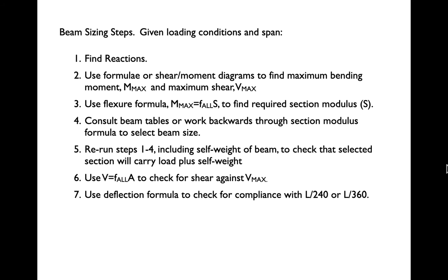And then finally, we'll use deflection formulas to calculate the beam's compliance with one of the two typical standards, either span over 240, which is a relatively loose, bouncy building, or span over 360, which is a little tighter.